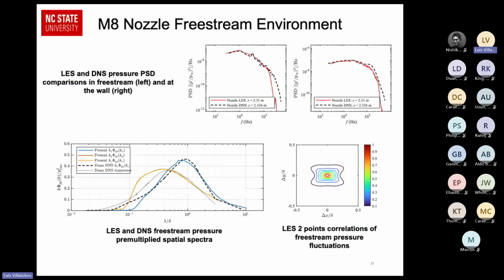And then for the Y and Z power spectral densities, we can see that we're agreeing well up until those middle frequencies where we're seeing a bunching up of energy occurring, where the DNS did not have that. So these are preliminary results, so we're still investigating why exactly this is happening. My running theory is that we are running an implicit LES, so maybe our numerics are not damping out the fluctuations appropriately, so perhaps the inclusion of a subgrid-scale model might improve the agreement there.